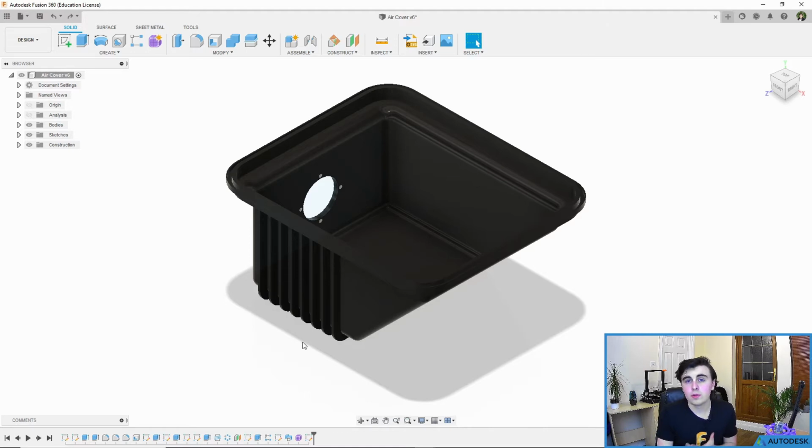It's really important that you try and use the timeline correctly. Otherwise, what happens is if you start deleting parts or changing parts differently, you'll get errors in your timeline when references are deleted and are no longer there. For example, if you extrude from a sketch, but then you go through and delete that sketch or change it, then you need to make sure that it's updated and the reference is still there. So making sure that you use this properly is something we will go through in quite a lot of detail to make sure you get it right.